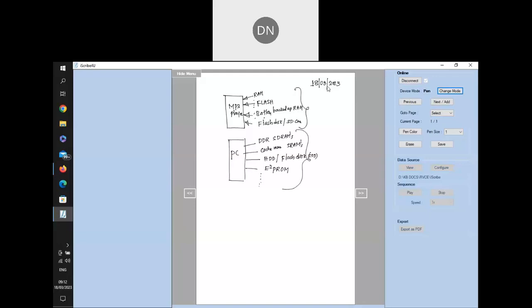So there are a number of types of memories present inside a single computer. If you ask why we can't use one type of memory to design a computer or an embedded system, it's not possible at all, because varieties of memories are required: the purpose is different, the investment is different, the speed is different. When we choose what type of memory is required, we should ask for what purpose it is required. If you want a small memory to boot, to start your computer and load the operating system from the disk to the main memory, you require a small EEPROM to hold that booting program.